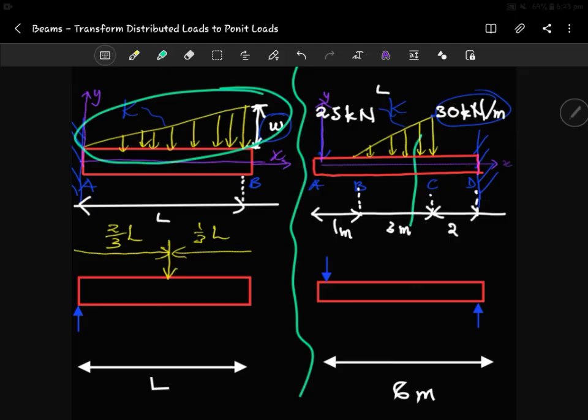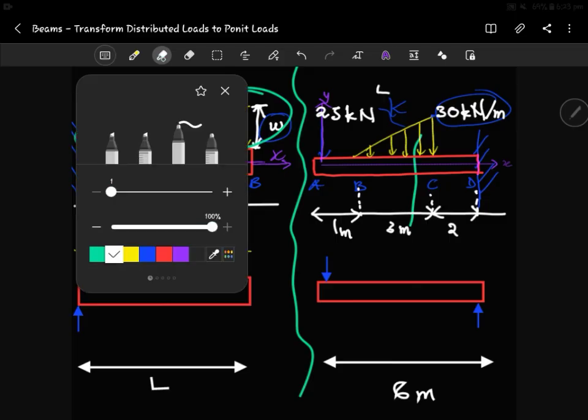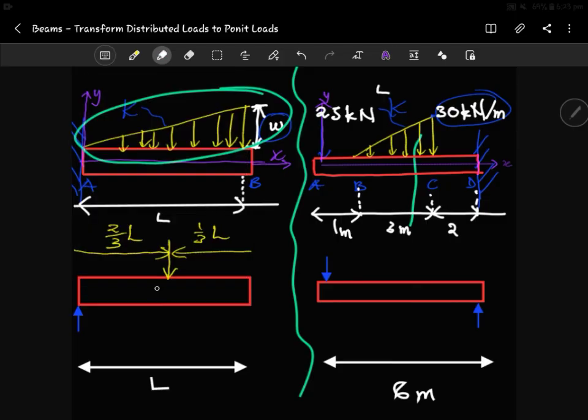So in order to get the point load, the magnitude of it will be half times base. It's acting on this whole length, right? And what's the height? The height is this, right? So this is basically a linear distributed load where we are using the uniform distributed symbol W to determine the height here. So this way, right? Let me put this somewhere properly.